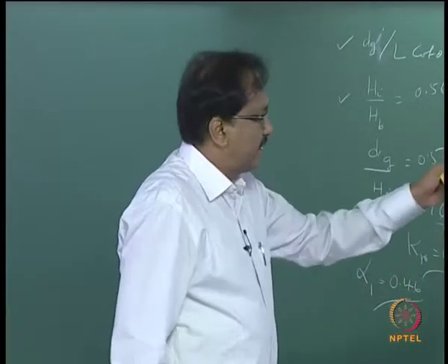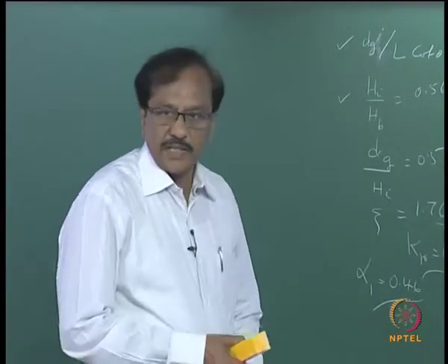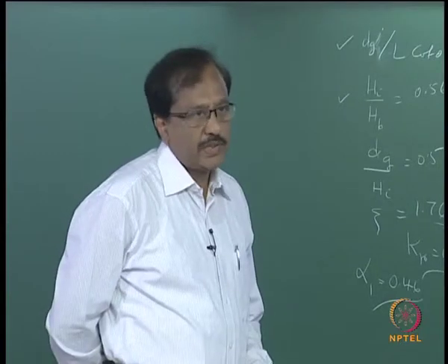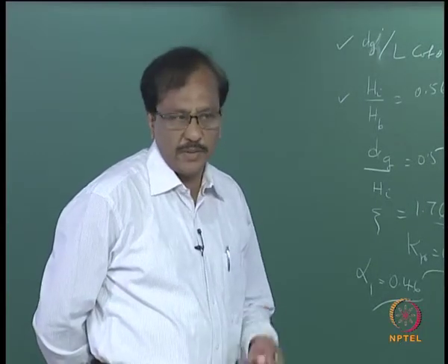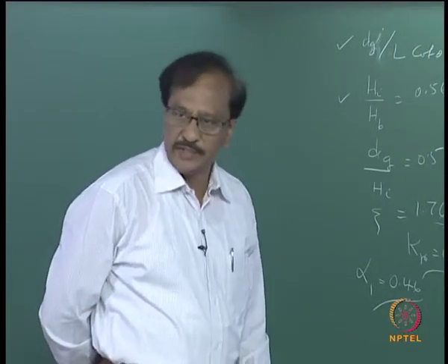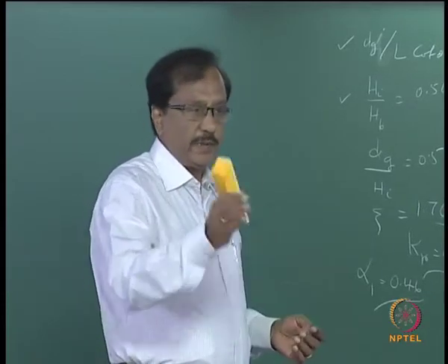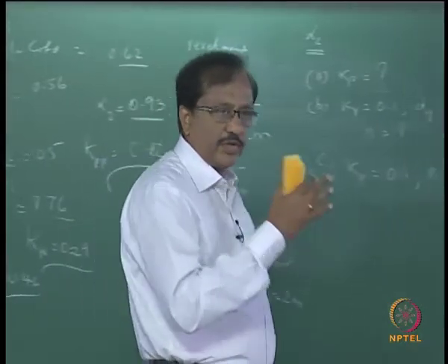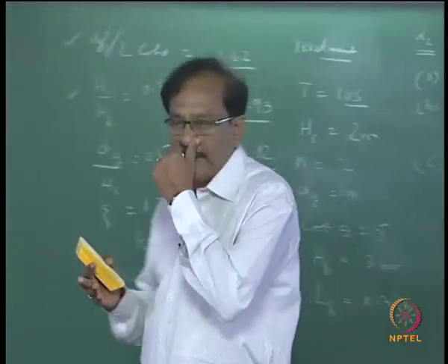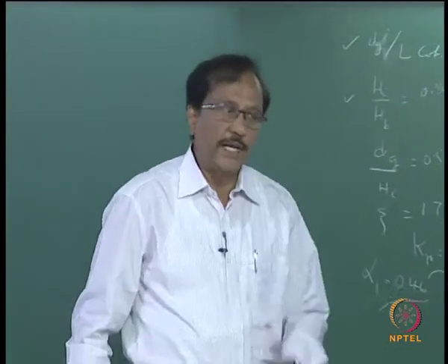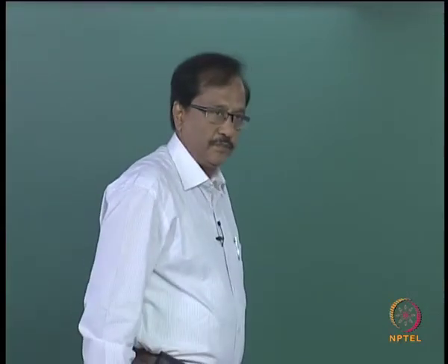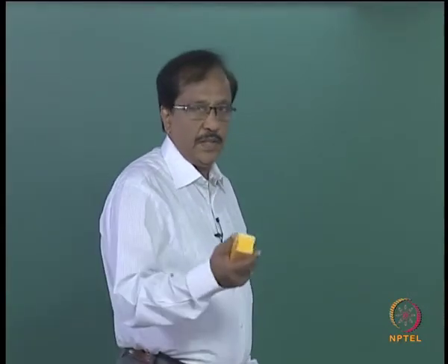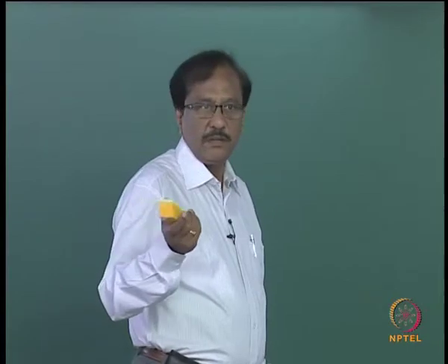So these are all extremely important when you are dealing with coastal rubble mound structures. Coastal rubble mound is also referred to as flexible structures, because when the wave is acting over the structure, some of the stones get moved and it can be replenished later. Any doubts? Okay, because this problem is quite simple.